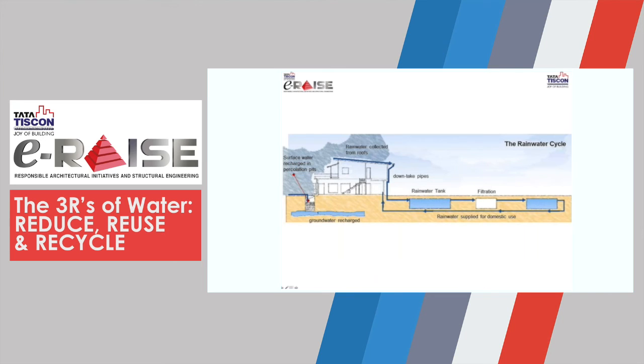Now, it is important to allow earth to also do its job. That is, the recharge well should actually not go right down to the aquifer. It should end before the aquifer so that the layers of earth get the chance to purify the water before it goes to the aquifer. Because endangering the aquifer, the groundwater table, is very, very dangerous.